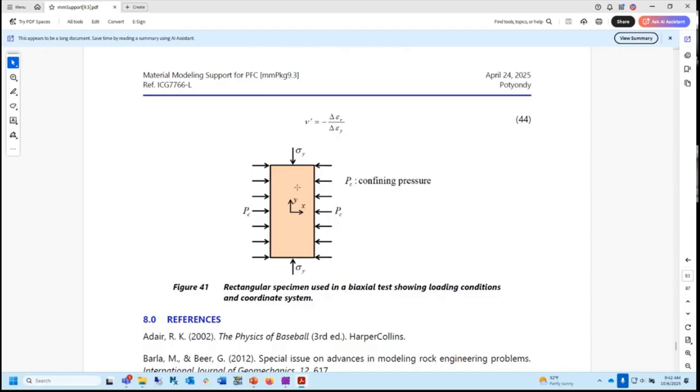They say, let's assume that the free surfaces are completely free and nothing is pushing against them. And what that means is that they call that plane stress. Think about this: you squeeze this, it's going to bulge out. Those free surfaces are going to bulge out, right? Because of the Poisson effect. Are you with me? If you took this and made it a plate, you squeeze it, it bulges out.